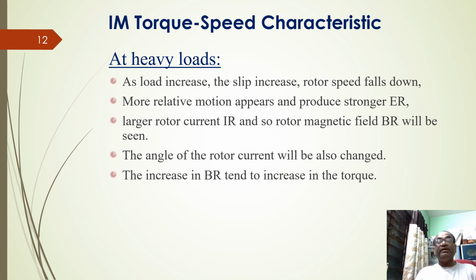So let me simplify it. Basically, what happens when your induction motor is loaded more, the more load tends the motor to decrease its speed. Consequently, what happens? The cutting of the flux decreases.